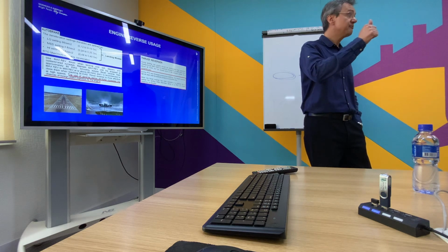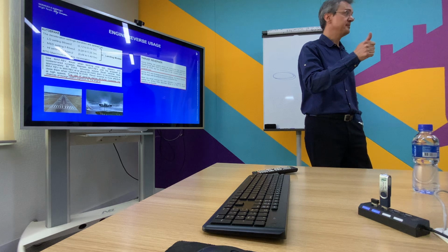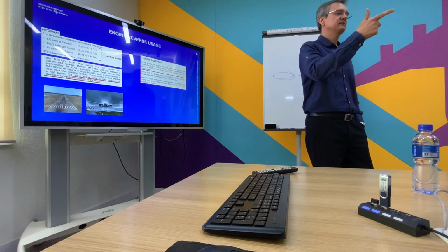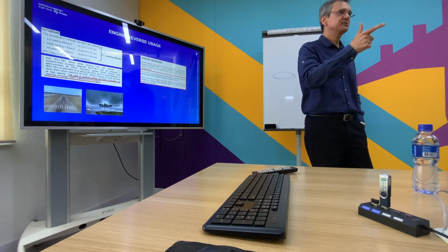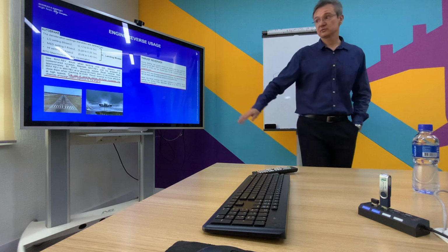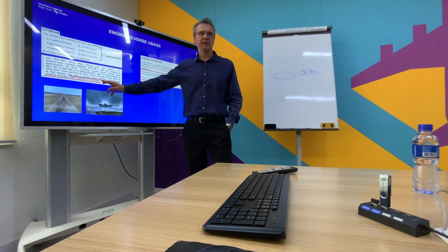We had only for reject takeoff the 60 knots. For normal landing we didn't have it at the beginning. And we updated that 60 knots during the landing. Whenever you hear this call out, pilot flying, stow the reverse because of this statement here on the manual. Okay.